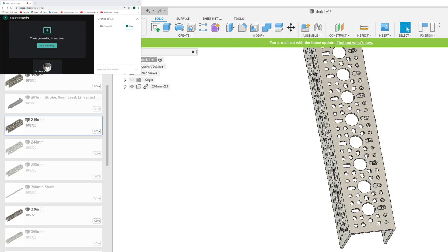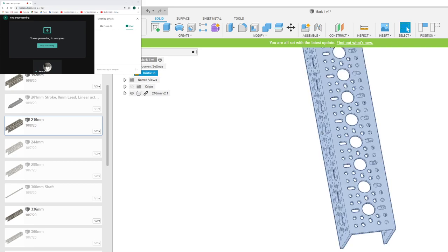You go to your browser and you click on this arrow next to document settings. Then you see this text that says unit inches, and then you just hover over it, and then click this icon next to it that should appear, and it says change active units. Then you get this little tab, and it says change active units, unit type inch, and we're going to change that to millimeter.